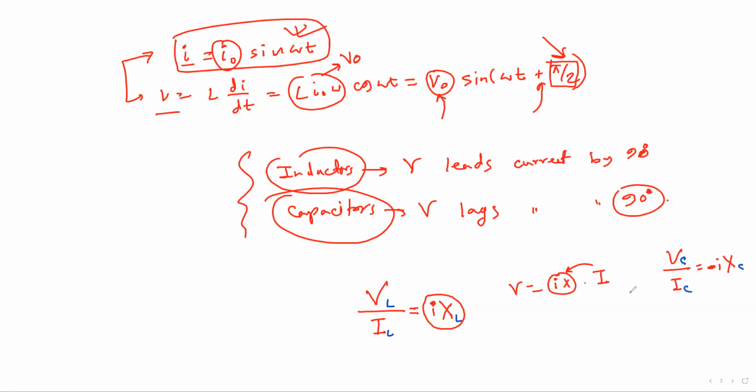And in circuits that have both resistors and capacitors, which are basically every circuit in the practical world, the overall voltage by current relation is generally something like a real part plus an imaginary part. So basically voltage by currents are generally complex numbers. So this kind of resistance-like object, which is not really resistance, is called impedance.